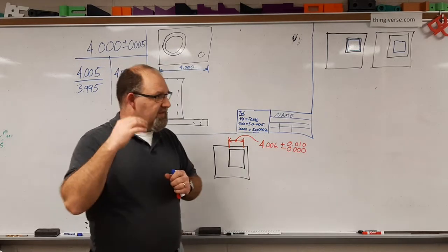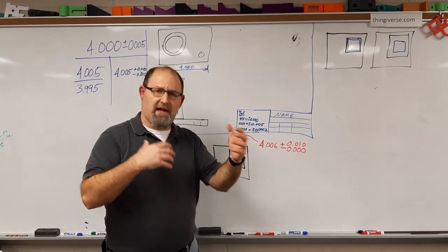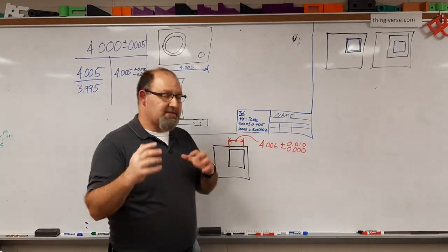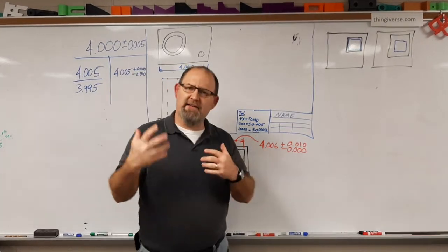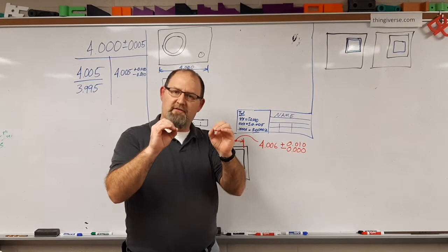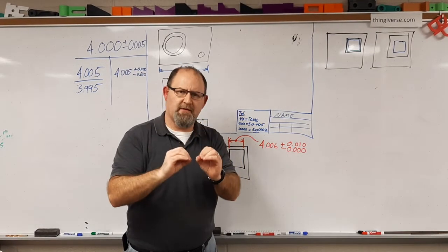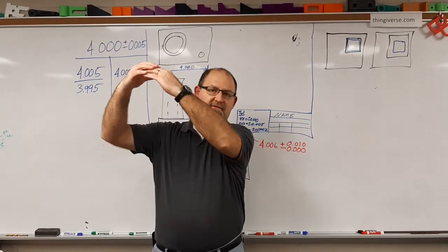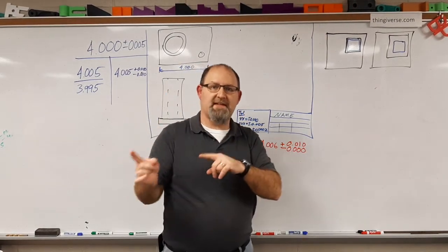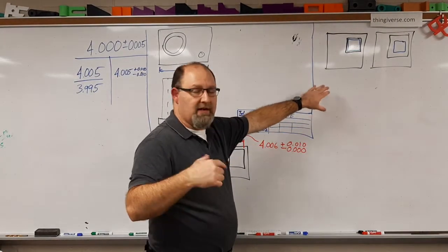Anytime you're doing this, if you're thinking about this for a quiz or a test, if you're calculating up tolerances, if you're calculating up what's called MMC and LMC, which we'll talk about in just a minute, maximum material condition or least material condition, it's a good rule of thumb in your mind as you're thinking about it. If you're comparing two holes, do not compare two holes that look about the same and one's barely smaller. You'll still be confused. Instead, think about it in terms of you've got a hole this big and you've got a hole this big as you're thinking through what's an MMC, what's an LMC, how do these mate up. Okay, so just keep that in the back of your mind as you're thinking through this process.